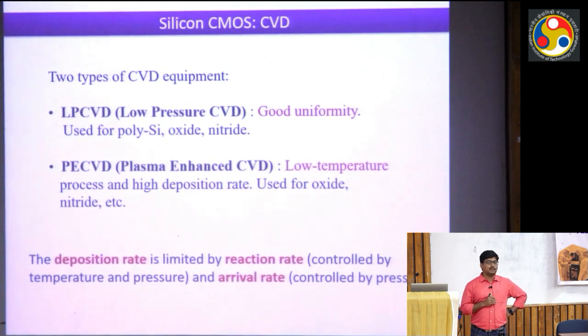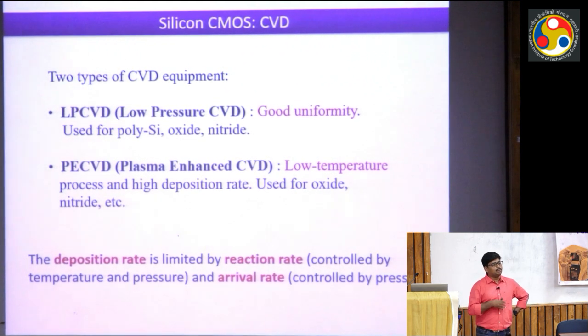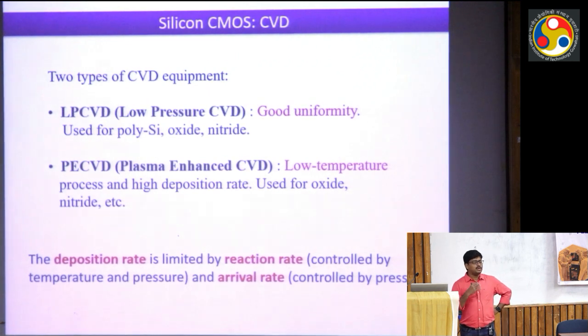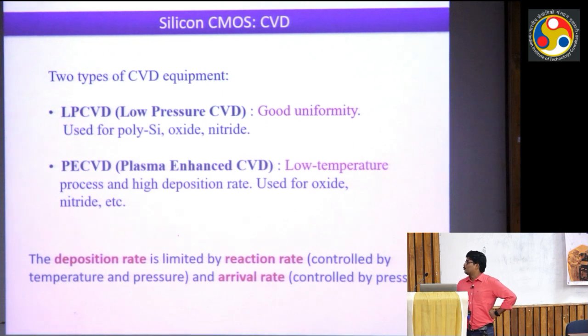So that we can get that in the case of PECVD, because PECVD stands for plasma enhanced CVD. So this plasma is actually helping us to get the same quality of the material without going to a higher temperature, without getting a higher electric bill, so we can still meet our requirement. So that is why this PECVD has another advantage compared to LPCVD or other high temperature processes.